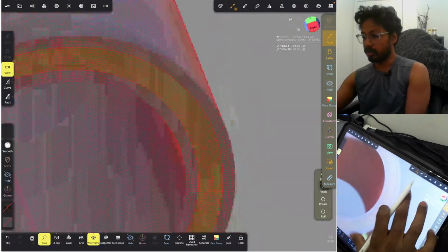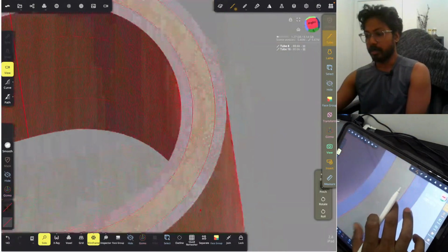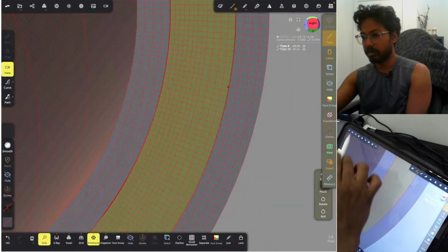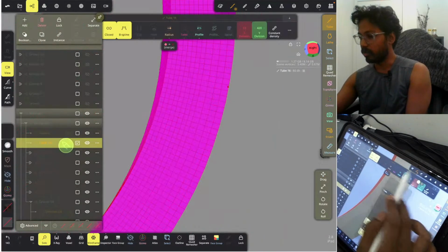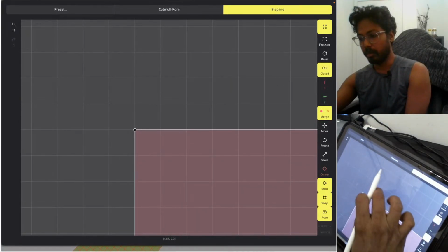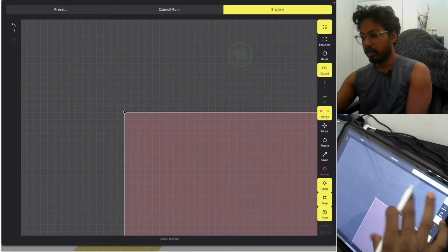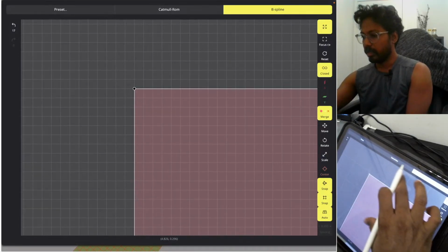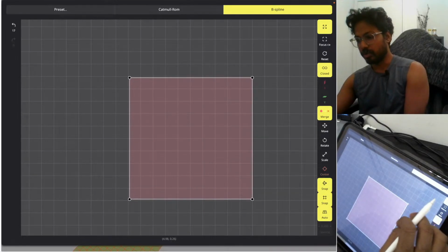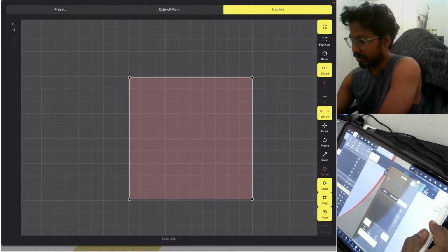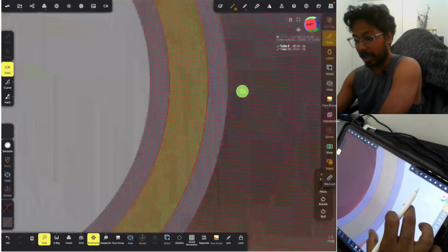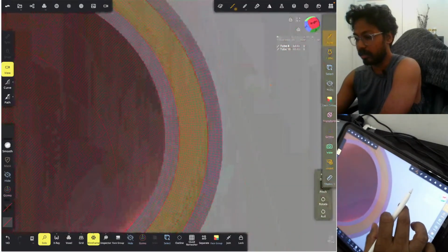And if you struggle, let's say you printed it and this tolerance was not enough, you can go edit it again, go edit profile, go there, and maybe add another 0.5 or 0.05 mm. You can zoom in and adjust, and this gives full control over the dimensions of the bodies, and that means you can get actual tolerance closer to a CAD design software.